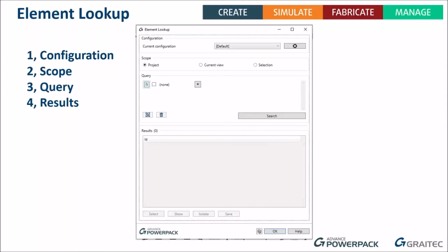And this is where, if you want to select elements in Revit, it's very limited in the way that we select elements. We can select it by category, we can select it by family type, but you're very restricted. And once you've gone to the point where it's by category, trying to then filter that information, even if you did a large selection in Revit, you go to the filter selection, the only option you've got in there is to filter by category. So you can deselect an entire category, but what happens if you only want to deselect certain elements in that category?